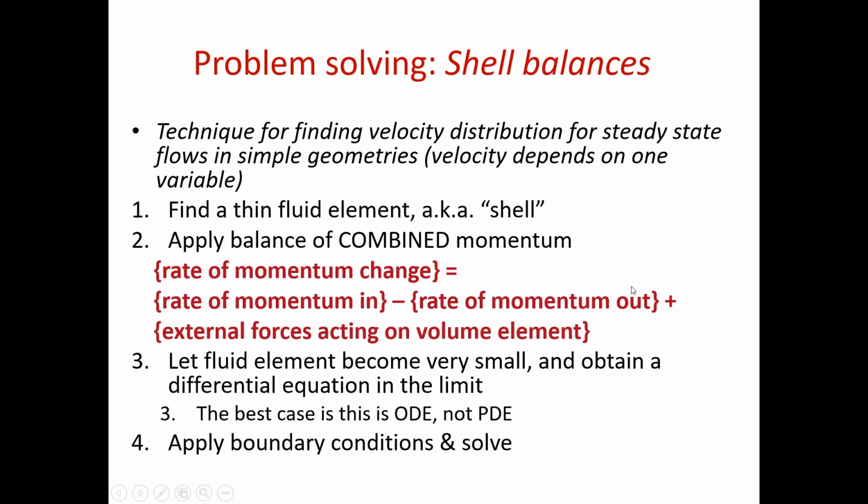So we have introduced general shell balances. Whenever I say shell, I'm defining a little, small piece of fluid that is aligned with my coordinate system. So I'm looking at a little box in my coordinate system. It's a box in a Cartesian coordinate system. In cylindrical, it is quite literally a shell, right? A little annulus.